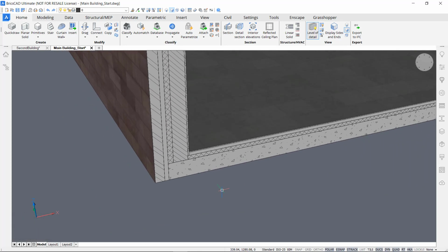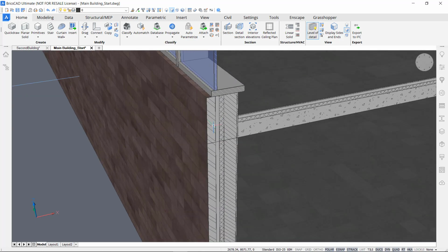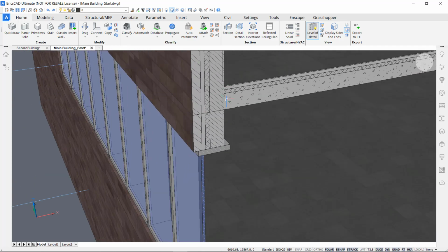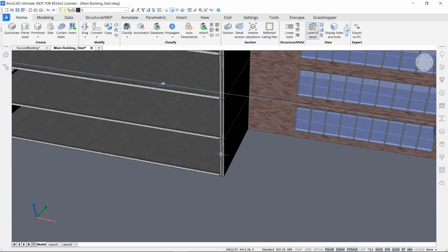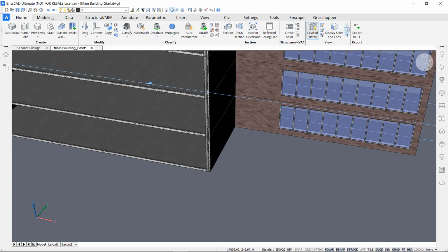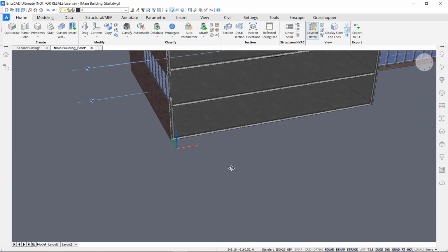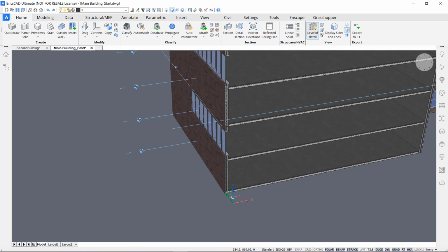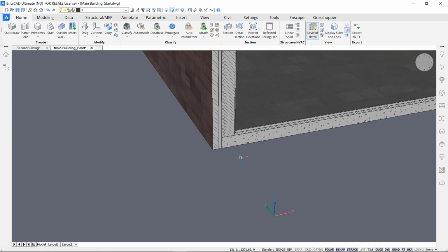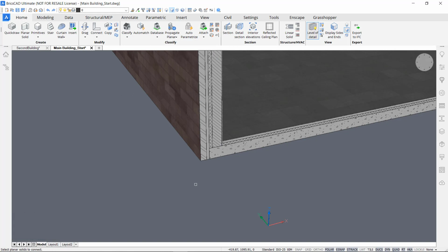Of course, if you see here or like here, these are all wall slab connections with the same kind of situation as the detail we just edited. We actually want this detail all over the rest of the wall slab connections, and we can do that by Propagate. In this case, this is Propagate Planar, and it searches the entire drawing for similar situations so that Propagate can copy this, applying this detail to the other places.